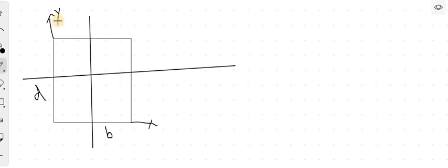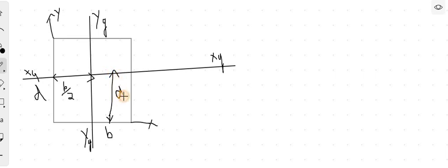Yes. What you have to do? You mark the centroidal axis at the center. Approximately, we don't know where it is, but according to our formulas, from Y to Yg, the distance is b by 2, which is the x bar, right? And similarly, what is y bar? Distance from X to Xg. So what is that? D by 2. You got it? B by 2, D by 2.